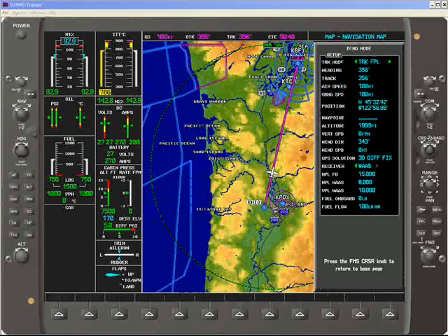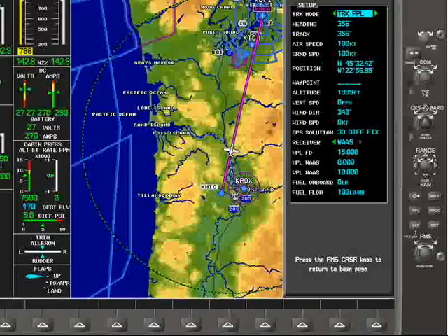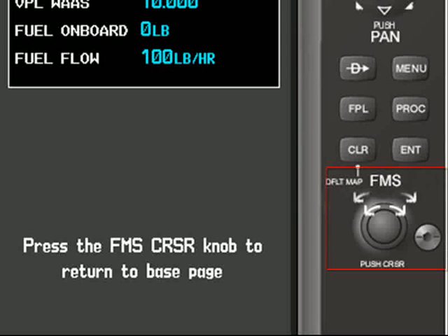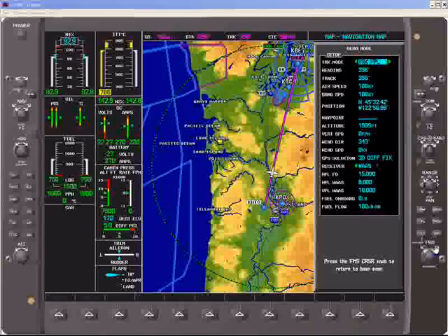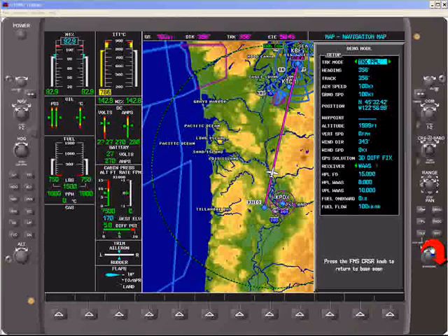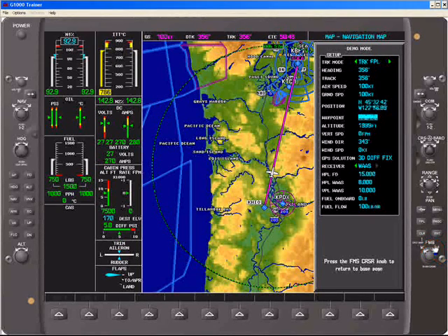With the demo mode window open, use the FMS knob to move the cursor and select the appropriate value to configure the flight parameters. The FMS knob is located on the lower right corner of the display. There are two knobs, outer knob and inner knob, or big and small. The big knob will move the cursor between the different fields, and the small FMS knob will allow you to change the value within the selected field.